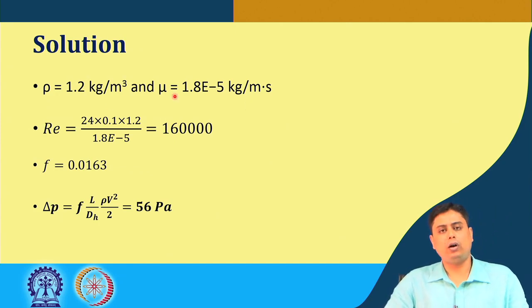So, now in order to find out the overall pressure drop, which is directly linked with the flow parameter, the Reynolds number, or how the flow pattern is, whether it is laminar or turbulent, because based on that you can use a particular drag coefficient or the friction factor. So, for that at first we have to calculate the Reynolds number of the flow for the scenario when there is no flat plate inserted. So, flow through duct, calculate Reynolds number.